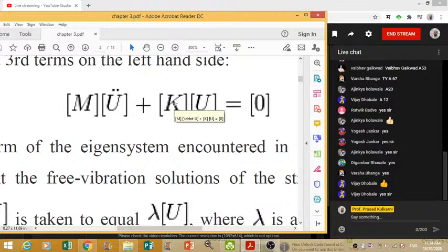Some students in the last year or previous years used to do the analysis on ANSYS software. They used to go for elastic modulus and Poisson's ratio, but they were not preferring the density parameter. Density is very important in ANSYS or any kind of dynamic analysis. If you want accurate analysis, density must be there. Why should density be there? Because density is mass upon volume.